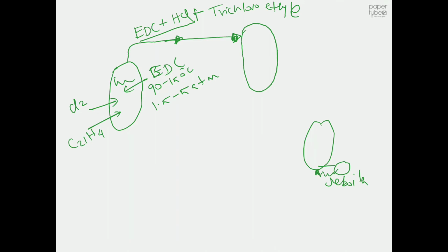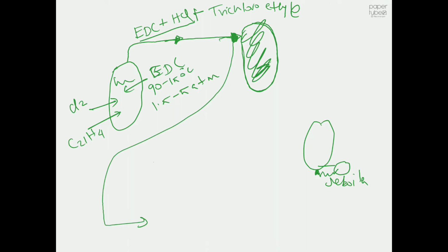But since your stream is already at a higher temperature, we don't need this reboiler in this setup. You just feed it into the column. Let's say we take the stream out, then we can feed it into the column like this. So this heated stream will automatically act like a natural reboiler.